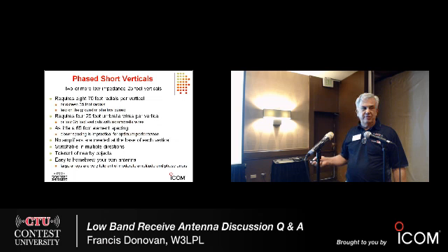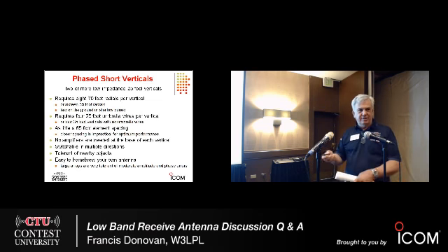No need for amplifiers. They are not needed. These antennas have about the same sensitivity as a Beverage. Some people find it convenient to put an amplifier in so their signal levels are about the same as a transmitting antenna, but it is not required. Not needed at all. They're very tolerant of nearby objects. You can put one of these antennas in a tree if you need to. You can put it on the side of a building if you need to. Now, if there are electrical circuits and other things in the building, it can cause problems. But these antennas are very tolerant.